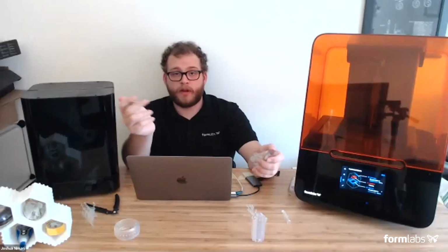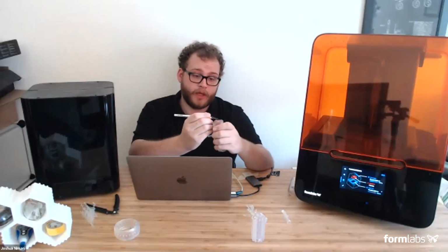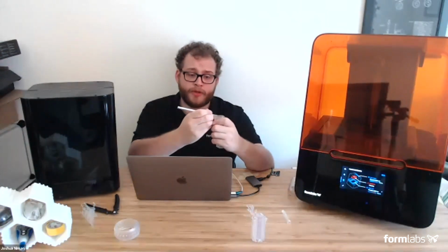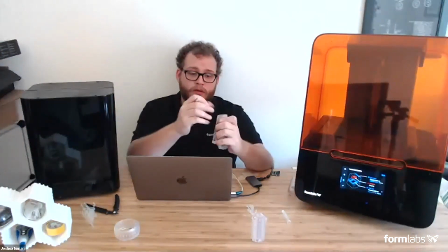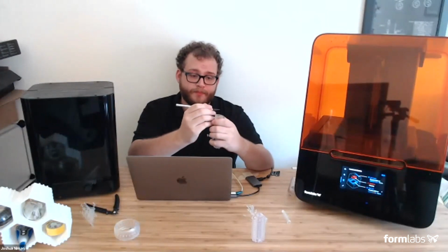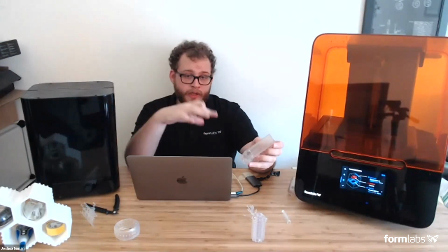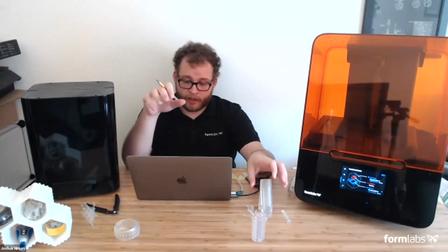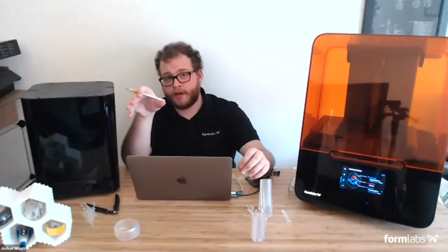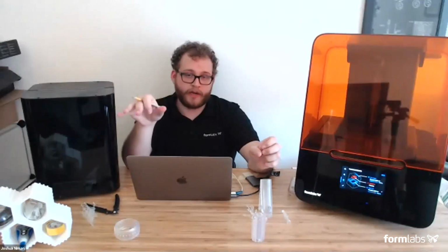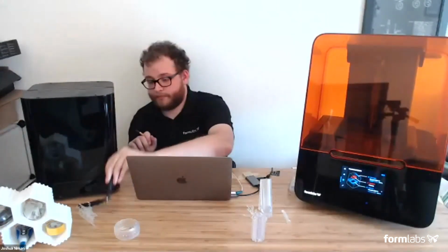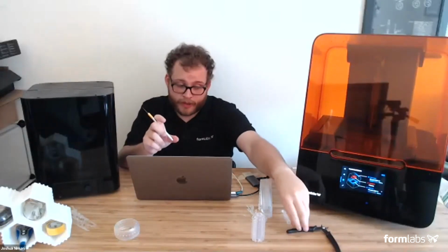Again, seems obvious, but a lot of people don't use them for this for whatever reason. This material is still hard enough that you can easily shave that away and do really nice, precise work, just taking them down to the surface of the part. So you can rip them. It's a lot easier to rip them with this new material, with these new settings. But if you want a perfect part and you want to minimize the amount of sanding you're going to have to do, or God forbid, trying to fill it with something, flush cutters followed by the X-Acto is the best way to do it.